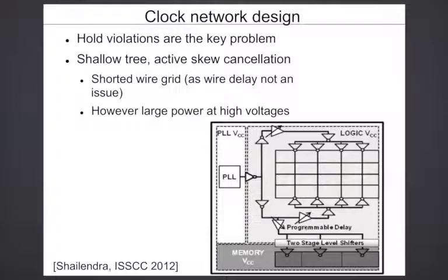So you look at what determines the delay. Delay is effectively an RC product, right? Resistance, the effective drive resistance of the gate, and the capacitance. So you have to adjust one or the other or both. That way you can adjust delay. So one way is to have a bank of capacitors which are controlled by a switch, and you decide how many to turn on or off. That way you can digitally adjust the delay.